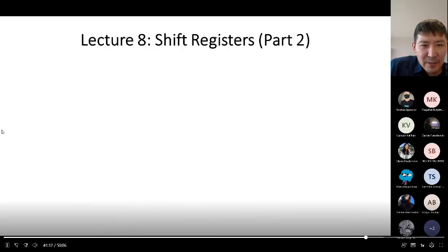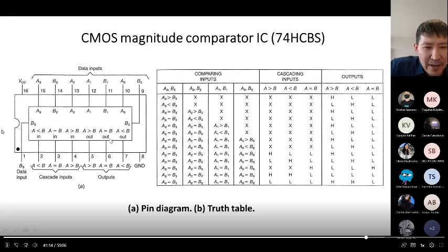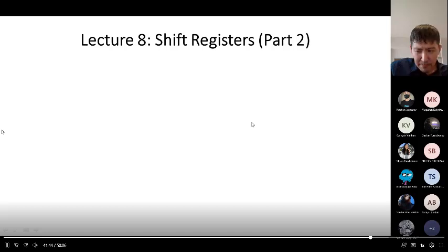So I've explained how this works, but here you need to look carefully for the comparator. It's a comparator, we will study it in detail later. It also has cascading inputs. Actually, you can connect two comparators together. Here in this example we compare a 4-bit number, but we can compare, for example, numbers encoded in 8-bit. Of course, this is the truth table of the comparator.